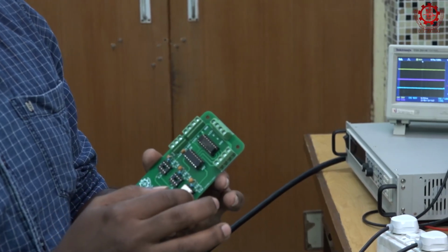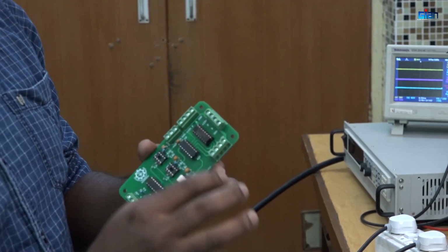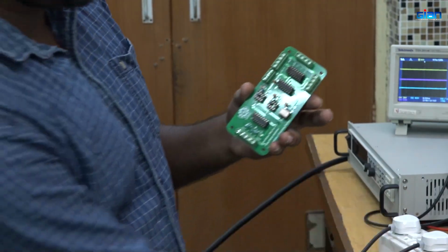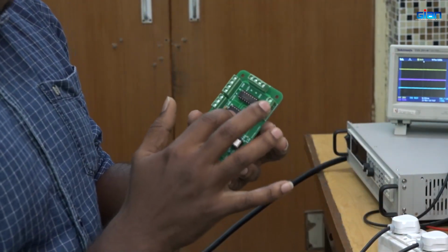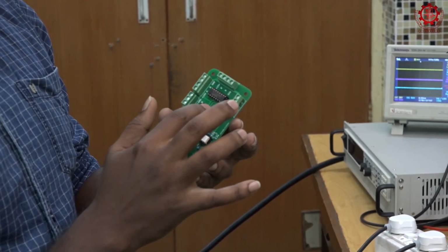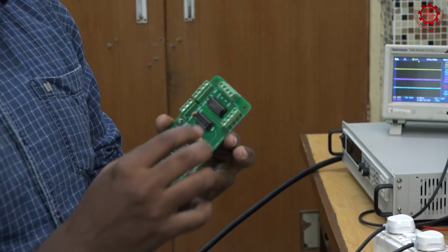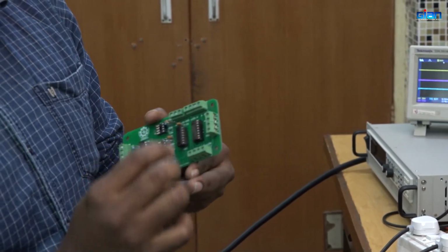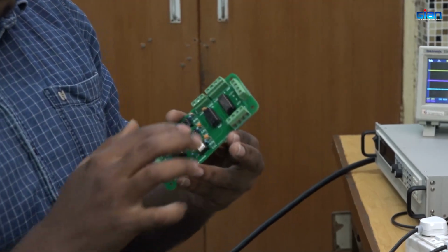We are giving an isolation for this, and this is the NOT gate. These should be operated with a 180 degrees phase shift. So there is an optocoupler. This is a NOT gate, where when the high pulse comes, it will make it off. So we have B dash. B is when a high pulse comes here. B dash means it will be a low pulse, with a 180 degrees phase shift.